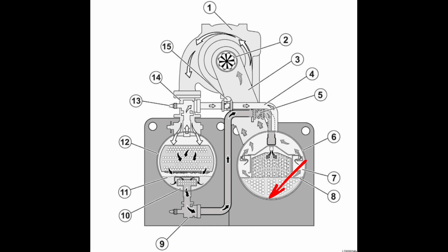And part of that is because that chiller runs such a low liquid level. The liquid level sensor, which is what controls the EEVs on that, is right at the bottom of the evaporator. It doesn't have a whole lot of liquid refrigerant in the evaporator, is part of my point. So they have the oil recovery intake right there at the bottom because, for the most part, there's not much refrigerant there to begin with.